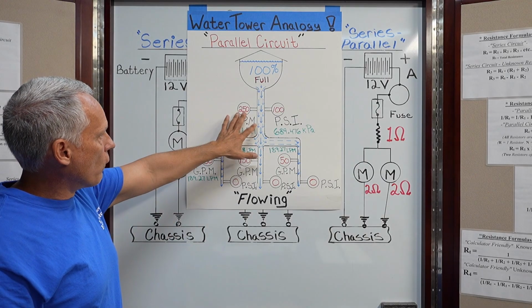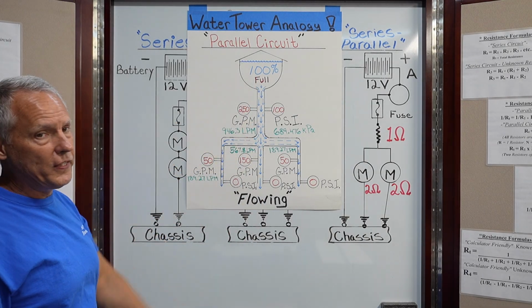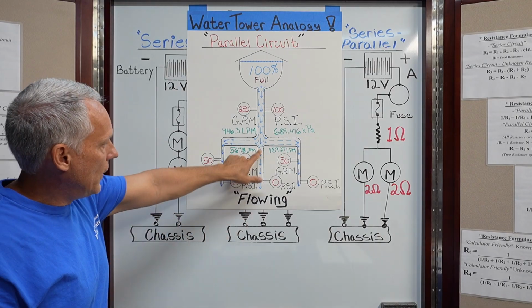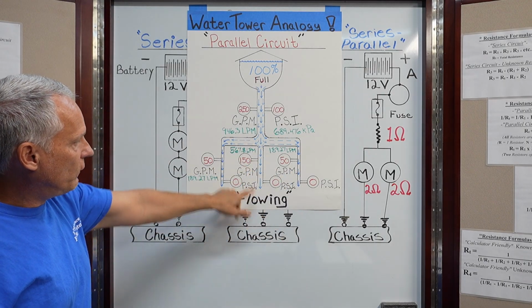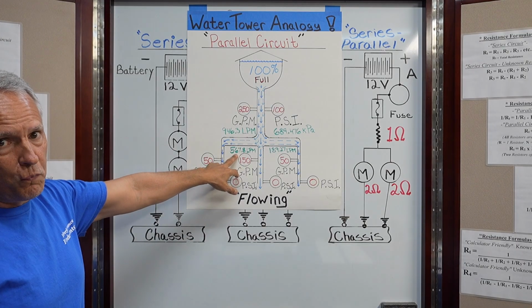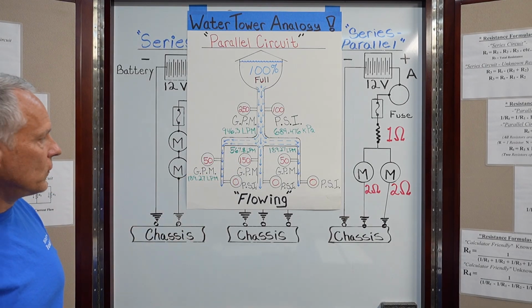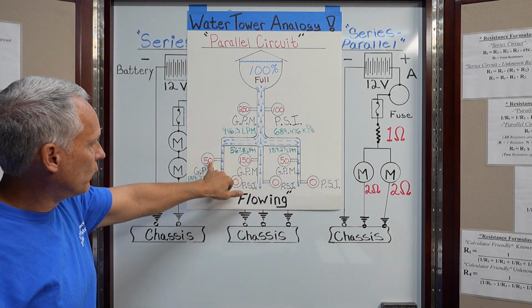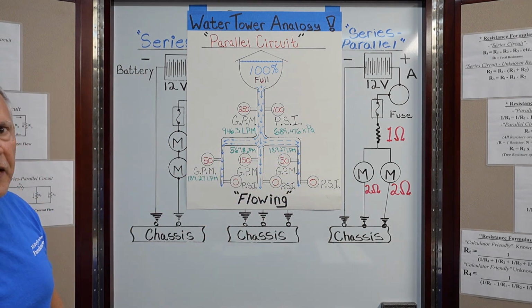We know that overall, we're calculating our total flow through that circuit. We're calculating it at 250 gallons per minute, right? This leg, or this branch, is larger than these 2. This one's flowing 150 gallons per minute, or 567.8 liters per minute. This one's flowing 50 gallons per minute, or 189.27 liters per minute. This one is equal to this one, so it's also flowing 50 gallons per minute, or 189.27 liters per minute.